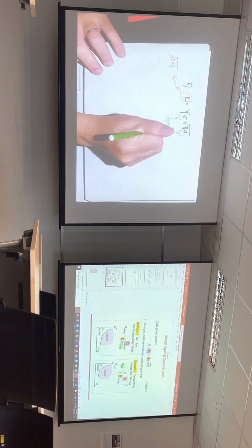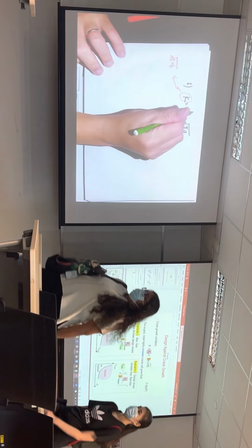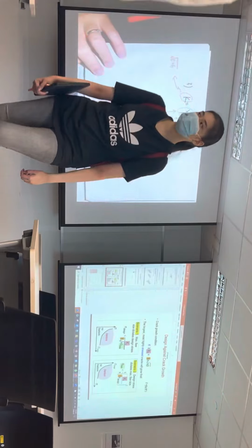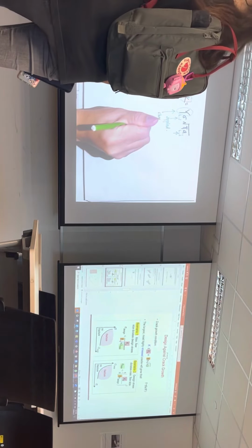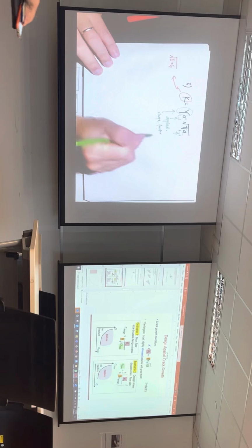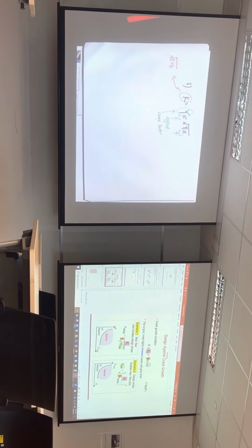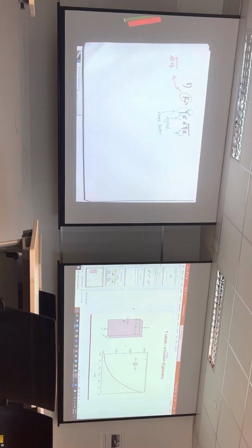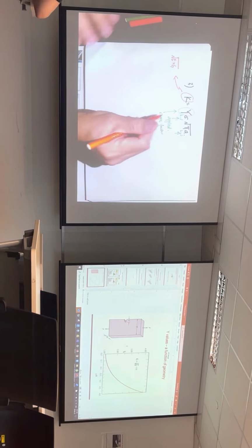This is the applied stress, same thing. And this one is basically a shape factor. This one is dependent on the design of the material. If you have an odd shape, then you have a certain shape factor. So this one you can always read it from, for example, over here. What is your Y value given a certain geometry? If A over W is 0.3, then your Y factor will be something. So it's really related to geometry. This is more of a geometry issue.